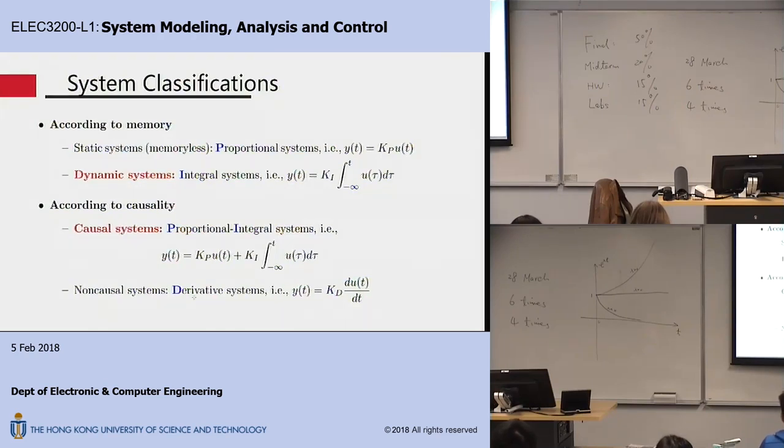The integrator takes the input and integrates it from minus infinity to t, and the integration gives the output. You see, of course, this system has memory. What happens in the past is going to show up in the integral, and it gives you a different value at any particular time. Possibly you have a gain, some kind of coefficient, in the I system.